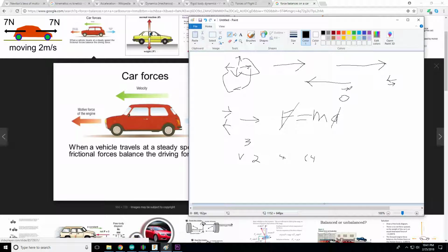But let's say, for argument's sake, that they are the exact same power no matter what speed. Eventually this drag, as velocity changes, cubes how large your drag is. It will eventually come up and equal your forward force from your motor, and that will mean you cease to be accelerating, which means you have a constant velocity. So that is now your max speed.